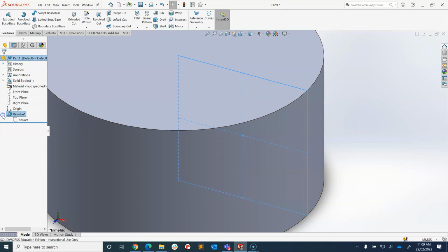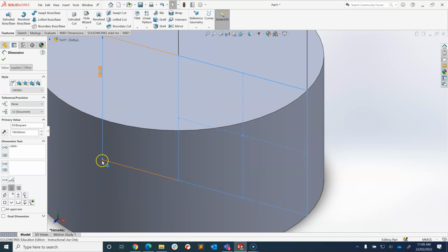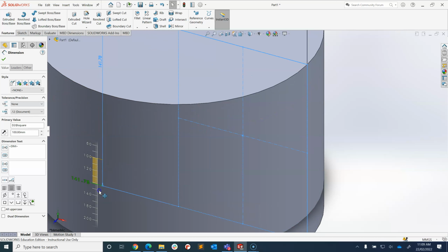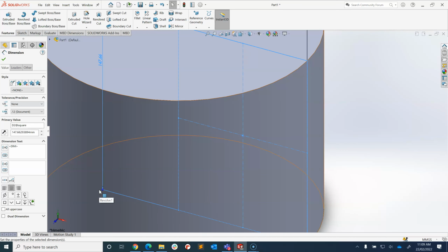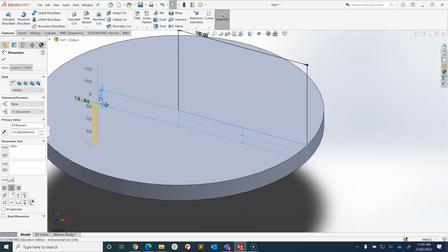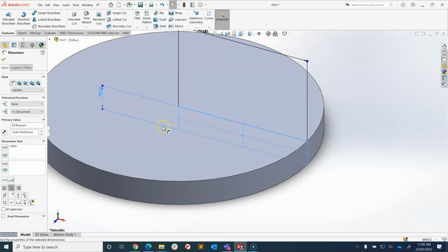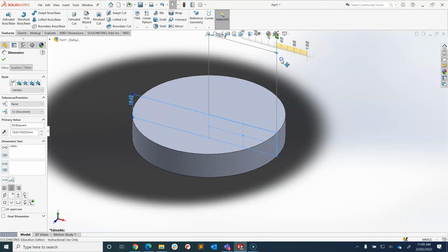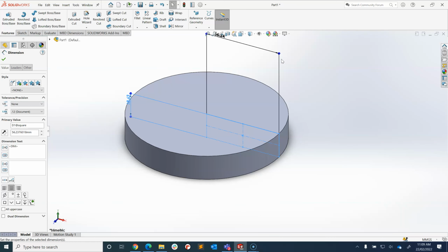And you'll notice here that this is called revolve, but inside there is our original square. It still exists, and we can still edit it, which is really handy. So if I want my cylinder to be taller, I can drag in that direction. And if I want it to be shorter, I can drag it in that direction. Same thing here, I can drag it in that direction. Okay, so that's a revolution. I'm now going to show an extrude.